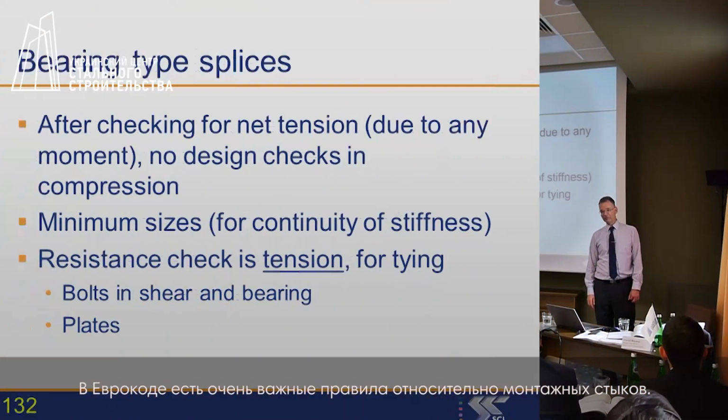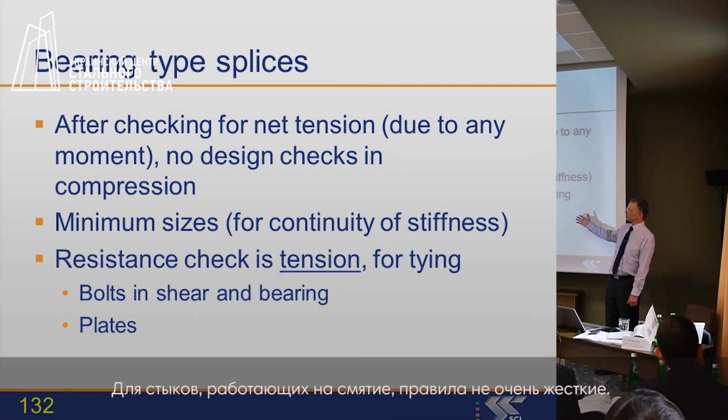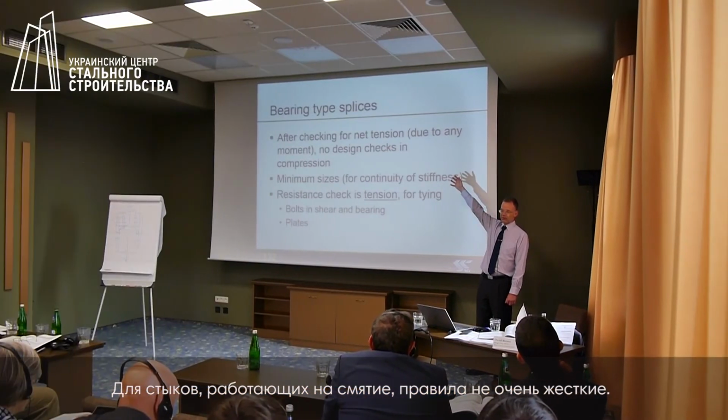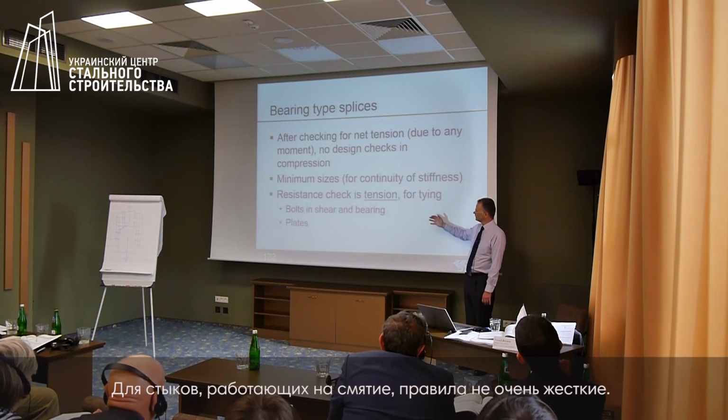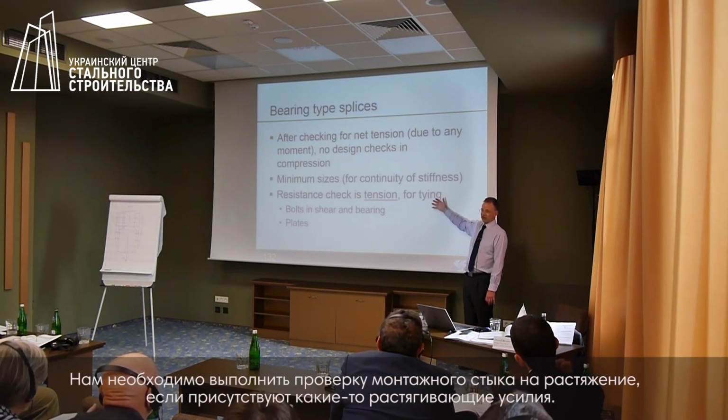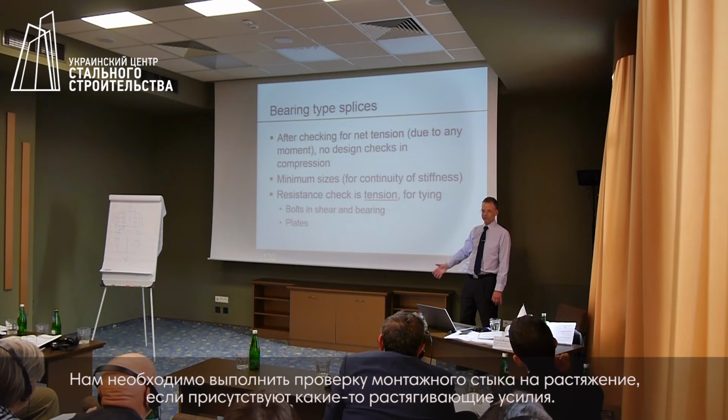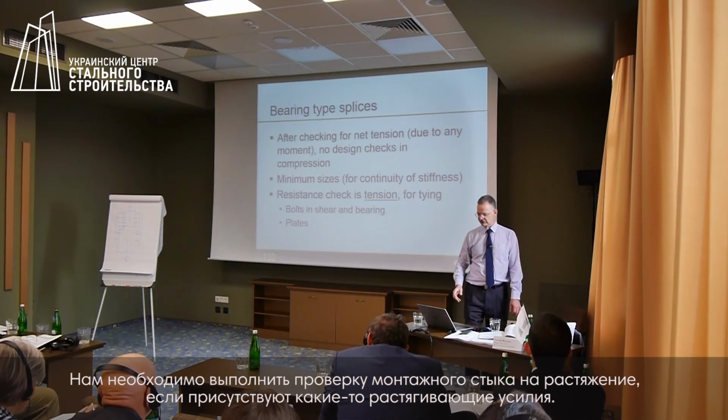The Eurocode has some very important rules for splices. For a bearing type splice, the rules are not very onerous. We would need to check the splice in tension if we have some tying forces applied.